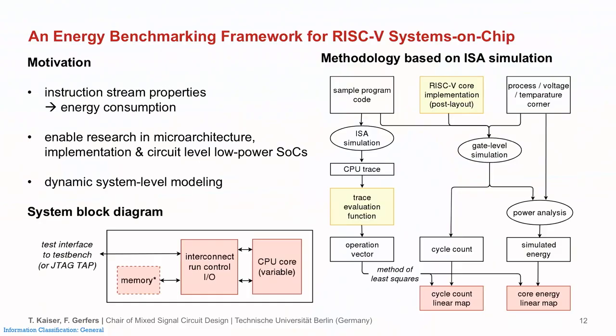Hello, I'm Tobias Kaiser from the Mixed Signal Circuit Design Group at TU Berlin. What I'm interested in is how instruction stream properties map to energy consumption in SoCs. This is of interest if you want to look at microarchitecture, implementation and circuit level design of low power SoCs. And what I do is I have a collection of sample program code that I'm running in two simulators, an instruction set simulator and a gate level simulation.